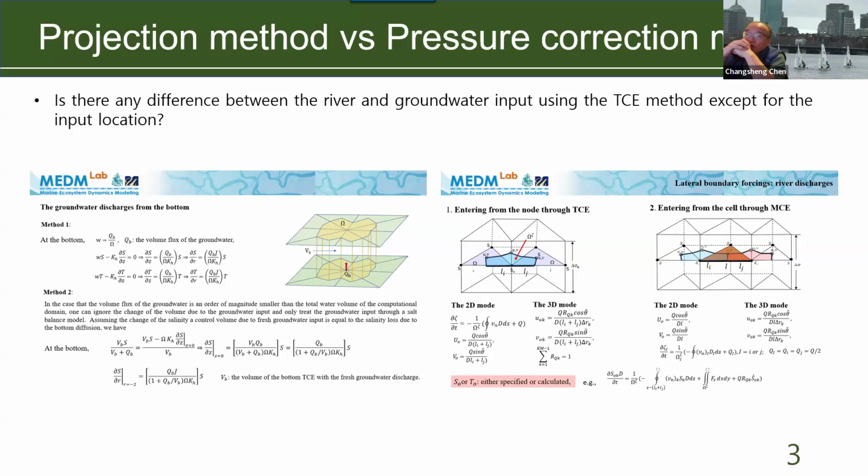So we also put the groundwater at the node point. The reason is that it comes from W. Because we calculate the vertical velocity W at the bottom, and now we are at a node point. Because of water conservation at the node point, you put a W there. That's why when you get groundwater, you also put it at the node point. You cannot put it in the cell, because the W velocity was at the node, right? So you need to consider the control volume, and put the groundwater at the point. When you put it in, you multiply by the area, the control volume. That's what the groundwater is.